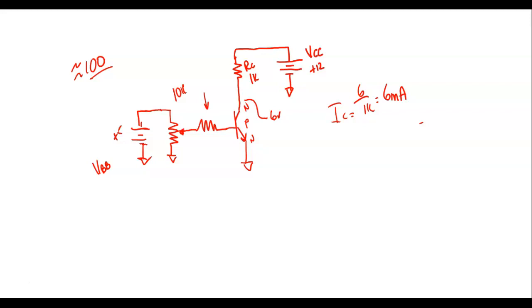You're kind of giving me that. Tell me what you're confused about. So if I came over here and gave you this series circuit right here, and I say I have no idea what that resistor is right there, but I know it's dropping 6 volts, and I know I got 12 volts right there. Okay, so we got 12 volts. So I know this guy. I know the size of this resistor, right? You understand? Okay, so that means I can calculate the current.